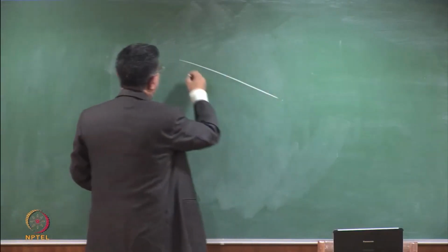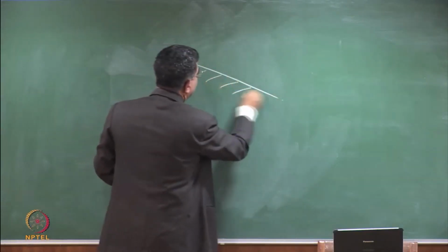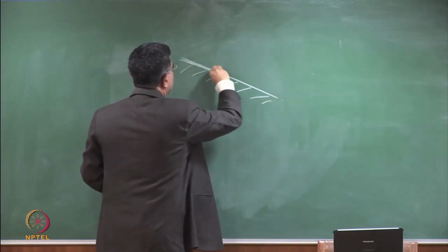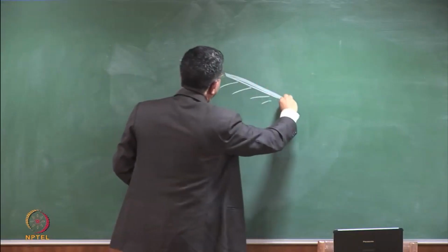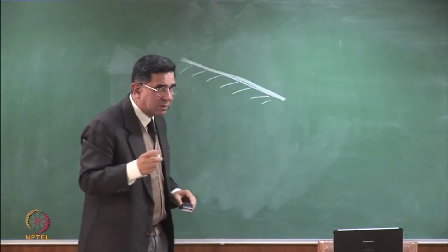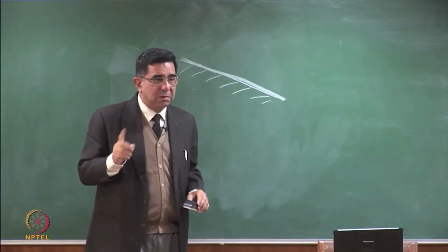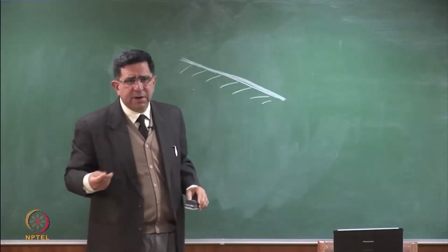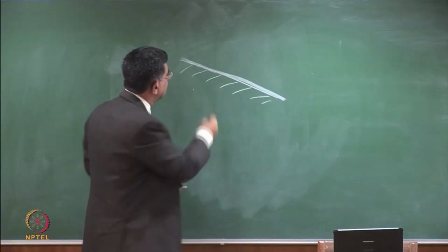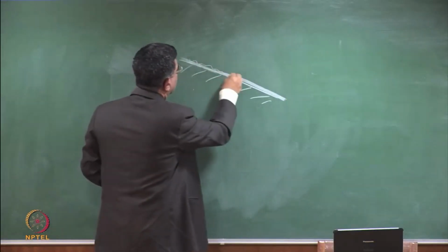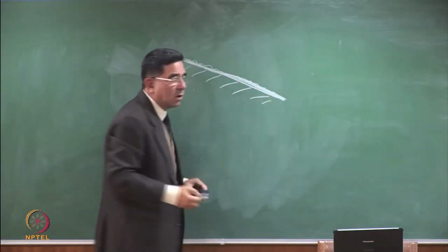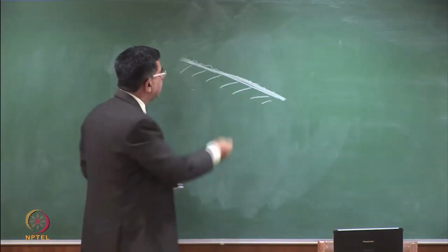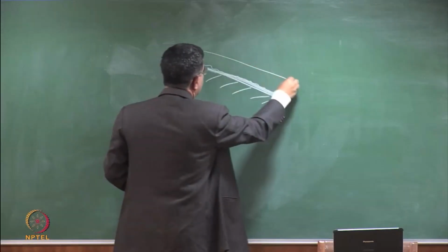Suppose this is the slope, this is my compacted clay barrier, and this is my geomembrane. Whether it's in the cover or in the liner, it's the same. I said smooth geomembranes are troublesome because the angle of shearing resistance is low. Let's make it rough, so now my angle of shearing resistance is not low. However, what is happening? I have a drainage layer on top.